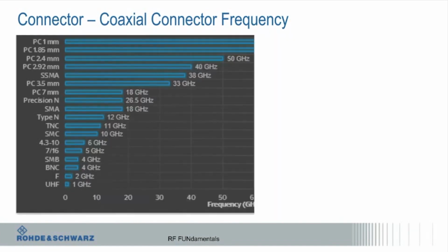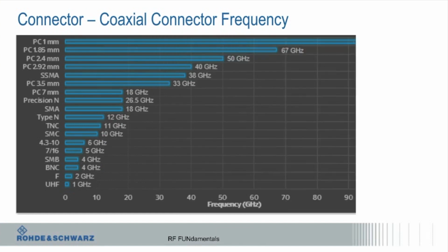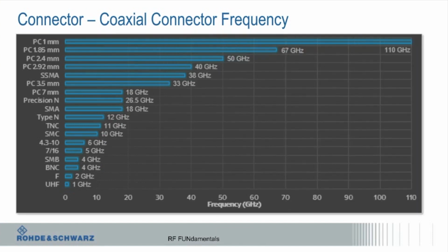Okay. The reason we beat these to death in terms of connector types is because people always use the wrong ones. They'll say, I have an SMA cable. I had a guy at a digital company with an SMA cable, and he was trying to measure something at 110 gigahertz. And guess what? It didn't work for squat. That's the 1 millimeter connector. I had to buy a bullet for doing a calibration of a 1 millimeter connector, and just one little part was $2,000.